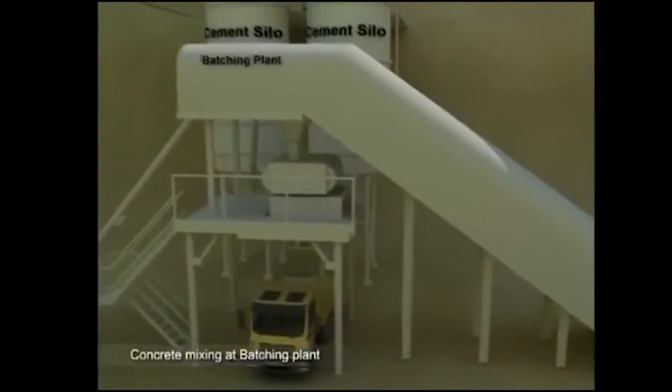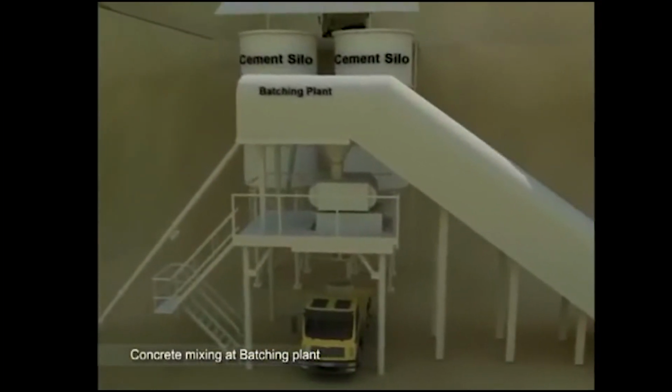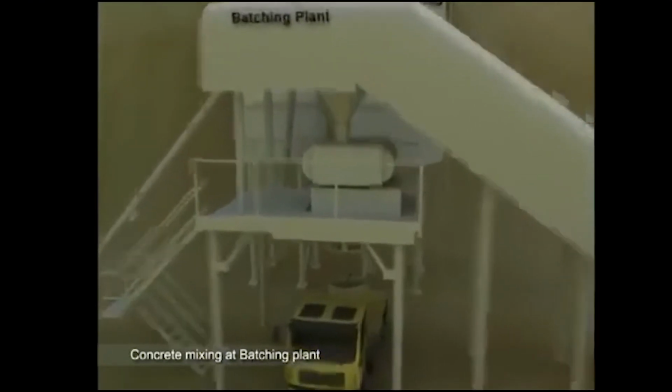At the batching plant, aggregates are mixed with cement coming from the cement silos and chilled water in the required proportions to make a concrete mix of the desired consistency. The concrete thus made is transferred into the concrete bucket placed on a truck that carries it to the dam location.